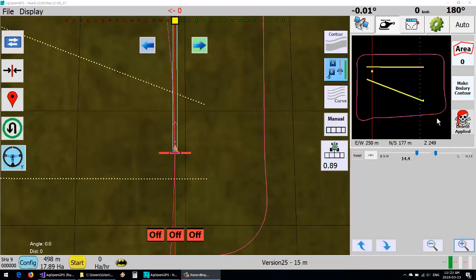Okay, we're talking about auto headland here, and when you have different slope or different angle of the headlands, how do you know when to turn the sections off and on, or do the auto headland controls? Because if we're just looking at the center, then it's before, here it's straight on, that sort of thing. What I've done is the same technique that uses the variable width to determine auto turnaround on AB curve.